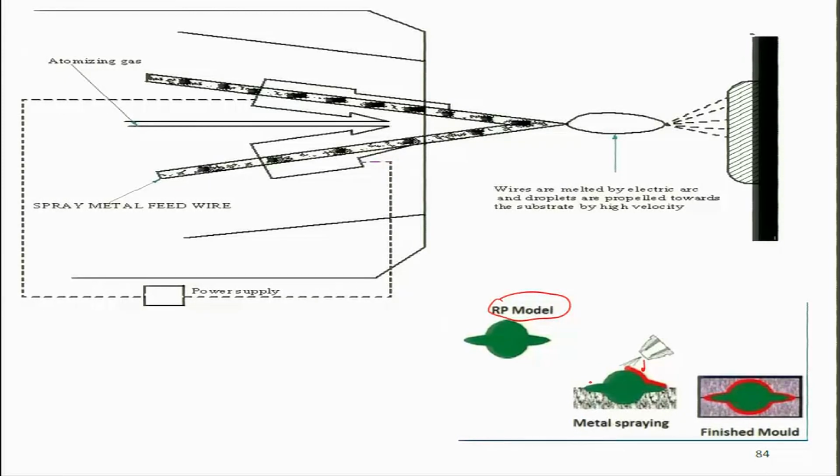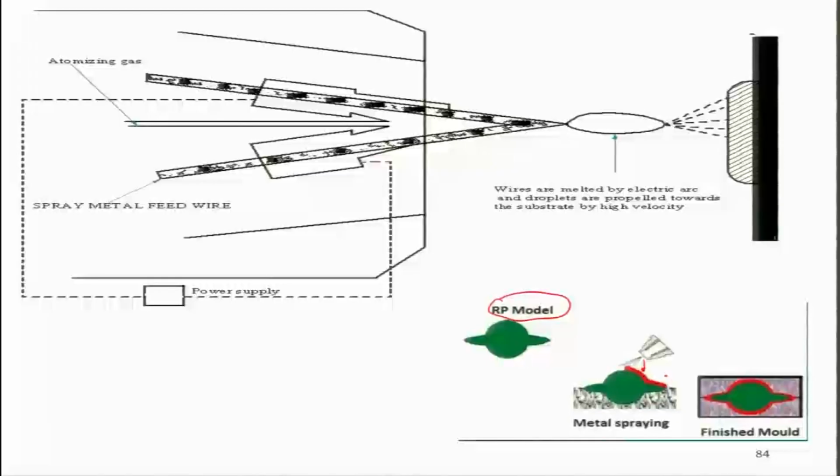So typically these metallized vapors are coated by creating two metal electrodes in an arc and then blowing an inert gas at a certain velocity through it, so that it can carry whatever metal melt has been formulated in that arc region, and can quickly atomize because of the high velocity. So now the atomized form of that liquid metal, which is being formulated at a small rate, can be considered to be like a metal mist, and this mist is actually coated on the top of the pattern,